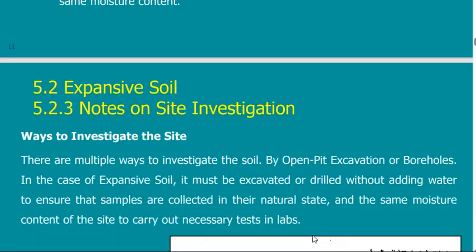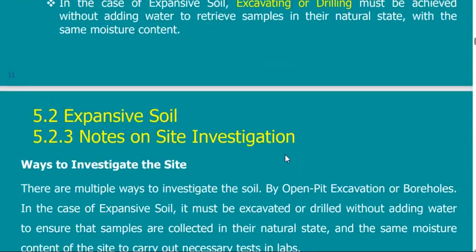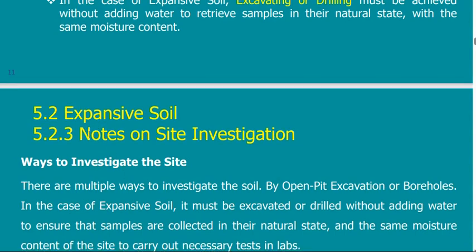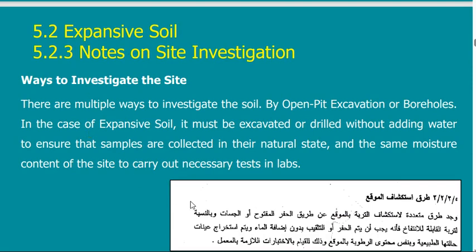Of course, if you hear the recorded lecture for this, you will find many details. How to find these types of soil, how to define them during site investigation. This is of course important, because in site investigation we use water. So in case I use water, maybe I would affect the problematic soil before getting the sample out.